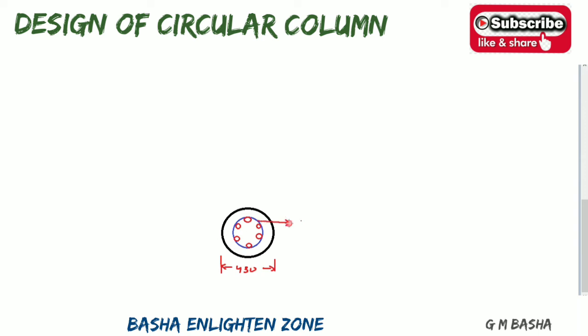So here provide lateral tie. So lateral tie is around, we are preferring 6 mm lateral tie. Okay, and 6 bars of 20 mm dia. Okay, so this is the cross section. This is the cross section.